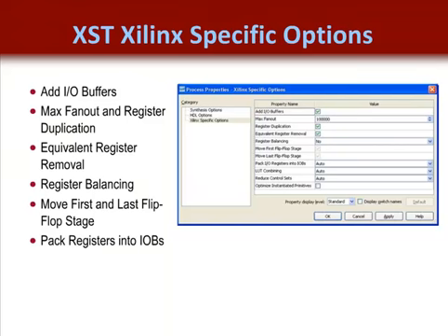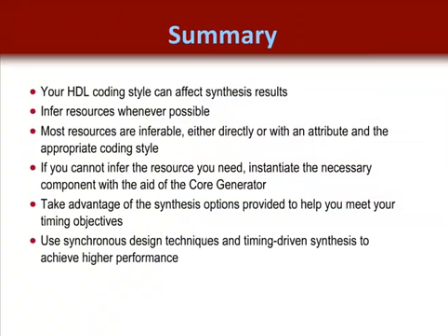And those are the most important synthesis options. If it all seems confusing, use just the options I've described and then experiment. Most application engineers would say, well, you can try this and try that. And you really shouldn't be too afraid, but I always tell people, start with this and go from there. Understand that your results might vary some, so keep in mind that your coding style, pipeline stages, and good synchronous design practices are more important to generating an optimal result than your synthesis options.